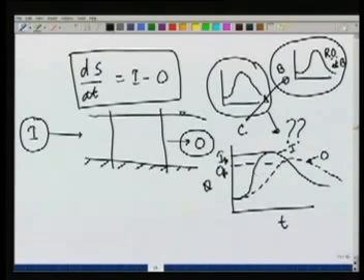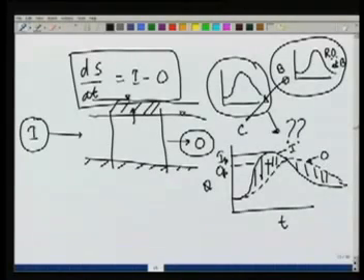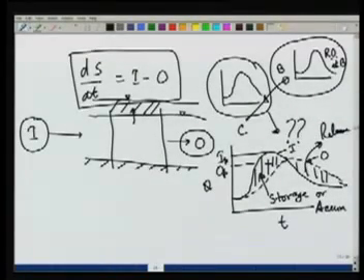If you look at this curve, the area before these two curves intersect represents that outflow is less than inflow, and therefore water is going into storage. And what is happening is that this water level is rising, and therefore the storage is increasing. So water is going into the storage up to this point, and beyond this point water is being released from storage. So we call this the storage or accumulation, and this release. So inflow more than outflow means water is going into storage, outflow more than inflow means water is coming from the storage or being released from the storage.